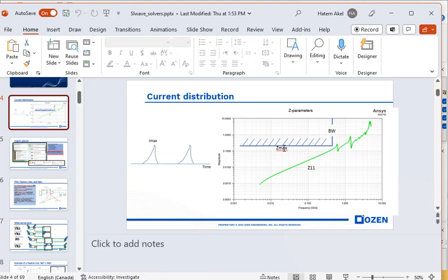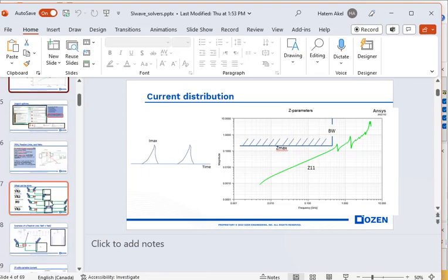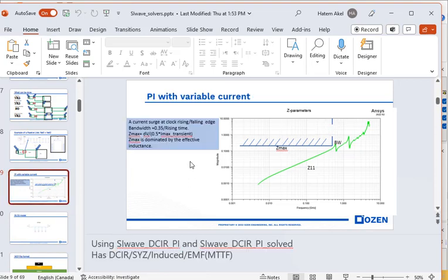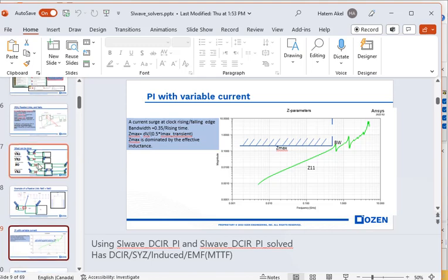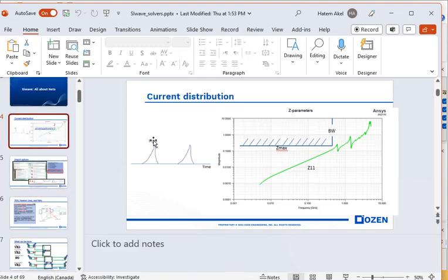And that's how we derive Z max. Practically there's a formula for Z max, and it's written here. It's delta V, the allowable voltage drop that we allow for our die, divided by 0.5 times I max. So if I go back to I max, it's this guy. What is the maximum current required by the die?